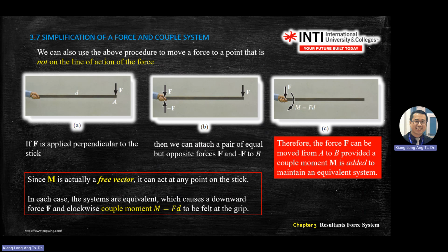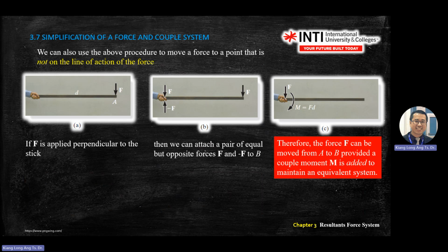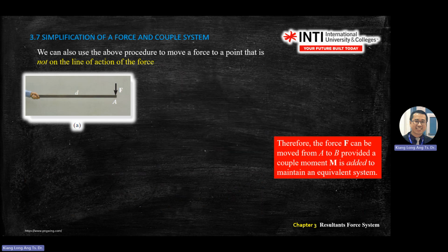In this case, F points down, so you are feeling anti-clockwise direction. So the moment that you transfer also needs to show the same direction. Don't go and change the direction. It's the reaction that you feel when you change the position of forces. So there are two diagrams, it's important.